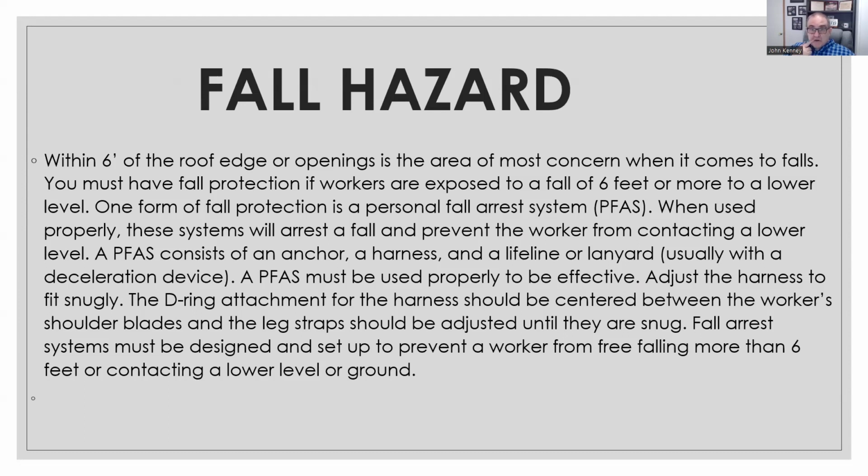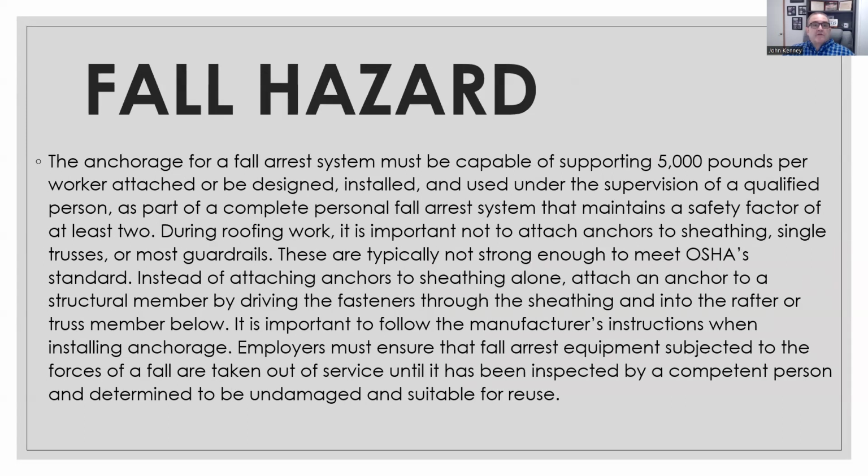So again, make sure you go through proper pre-training of all this and have your workers sign off through your training program, and then you've got them out there and they are trained and safe. The anchorage for a fall arrest system must be capable of supporting 5,000 pounds per worker attached, or be designed, installed, and used under the supervision of a qualified person, as part of a complete personal fall arrest system that maintains a safety factor of at least 2.